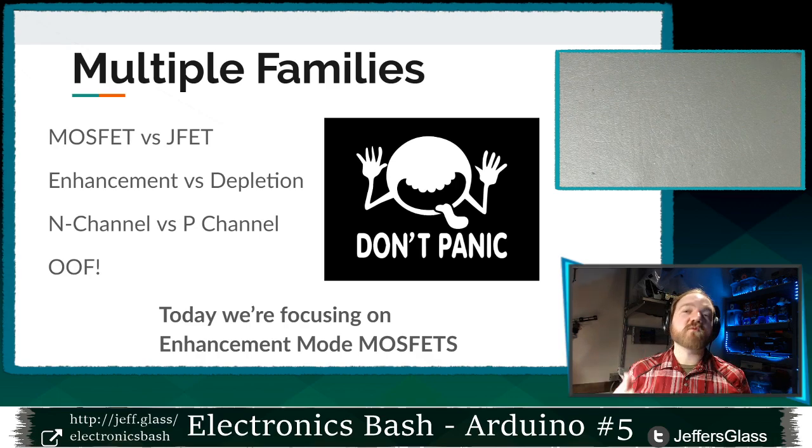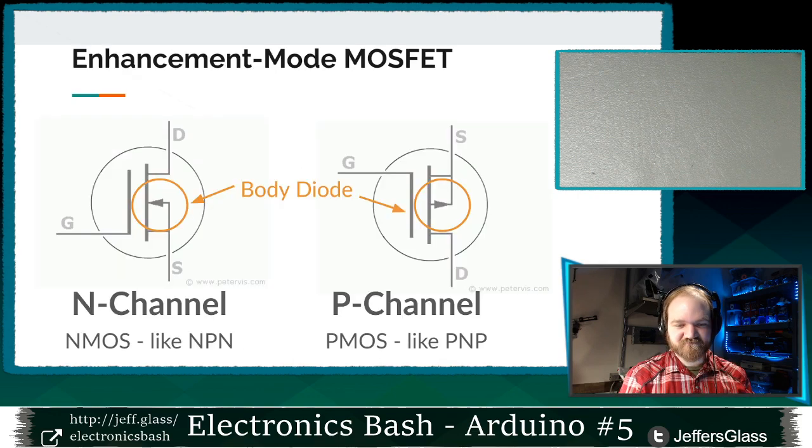I'll show you sort of when we get to the end why you might want to choose some of these other types, but if you're buying a MOSFET and you say, oh, it's an enhancement mode N-channel MOSFET, that's going to be fine for you. All the ones that are available on Adafruit and SparkFun, for example, are these enhancement mode MOSFETs, just to let you know.